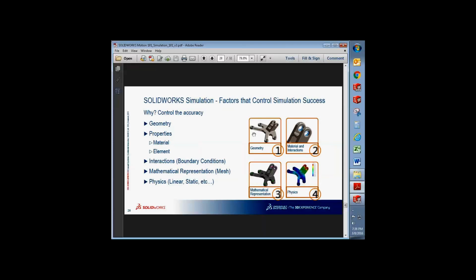You might put in very tiny fillets for aesthetic reasons, but for simulation, it's going to hurt efficiency, take a long time to solve, or just be too much detail for what you're trying to do. So that affects your results. The material you're using affects the results. Element type I will come to while I do the demo. It's almost like sometimes garbage in, garbage out.